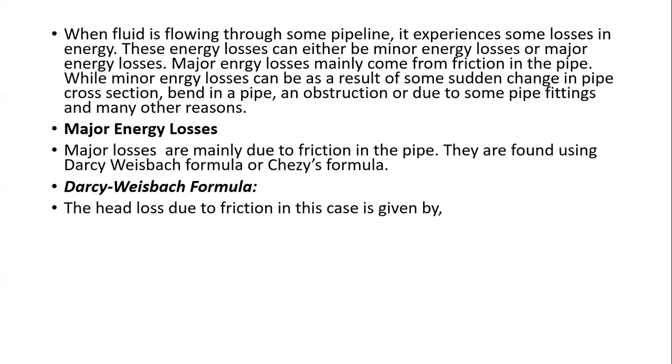The head loss coming from friction is given by hf = 4fLV²/2gD, or you can write it as 2fLV²/gD, because the 2 just cancels with the 4.